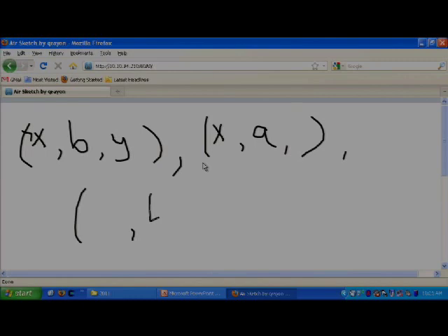Dima. Yeah, we have X and we are outputting Y, but in the future, if we stay in the initial state, we're not going to. Okay, so the question is, what happens if you actually got an X input when you were in state B and you output a Y? In temporal logic, this itself would satisfy X implies future Y, because when you talk about future Y, the time point starts right away.